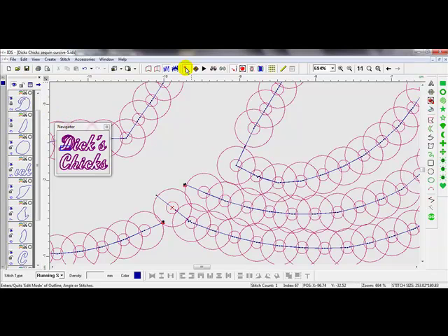So if I turn off the edit mode in the stitch view, I want to make sure I'm looking at my in and out points and they're okay. With the out point here, that means that it's going to stitch on top of the sequin. I might reverse those. So it starts there and ends there. And actually, I would need to unlock that and hit generate. So that means all the stitches that I had moved are going to go back.